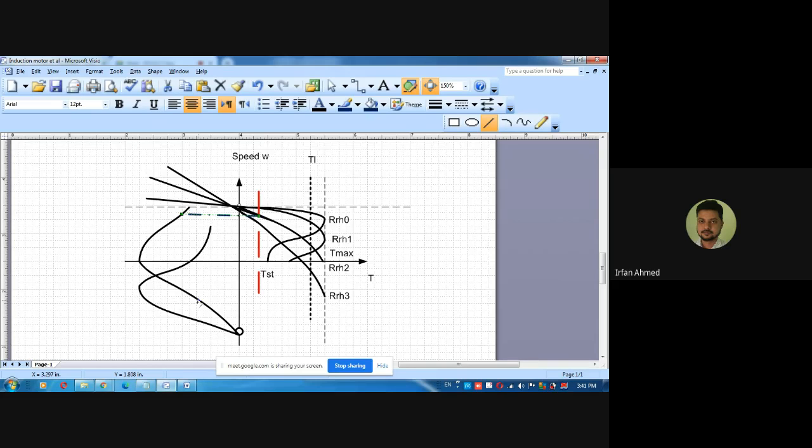There is also a third type of braking, that is dynamic braking or rheostatic braking. In case of a DC motor, we kept the field winding supply constant so that the flux remained constant, and we disconnected the armature and shunted a resistance across it. What do we do in case of induction motor? It has a three-phase stator winding, to which we were earlier feeding a three-phase supply, and there is no supply in the rotor. So how do you obtain dynamic braking in an induction motor?